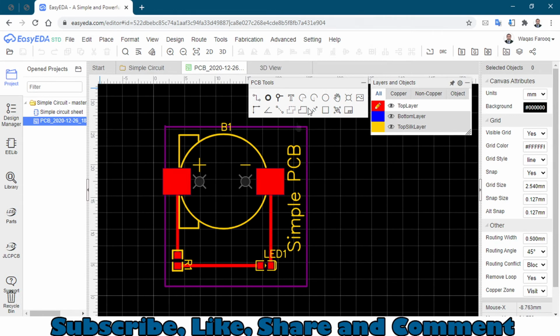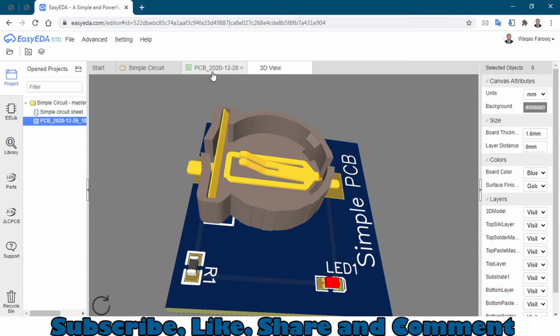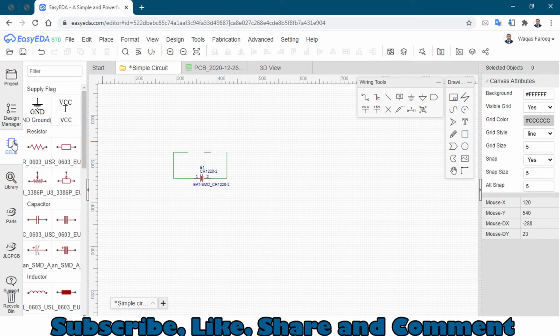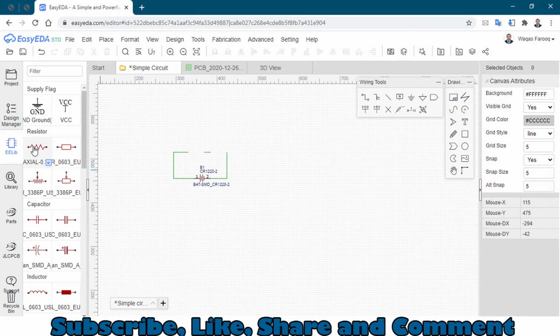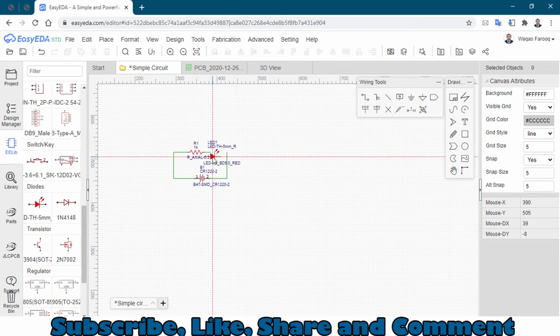Further moving into this tutorial, as I have mentioned, these are the SMD components. As you can see, these are surface mounted devices, so we can change them into THT devices. Like if I want to change this resistor, we have to go to the circuit diagram. Here I will delete this resistor and LED, and from the EE library I will select this axial resistor and bring it right here. And for the LED I will select a 5 mm LED and bring it right here. I have changed these components.